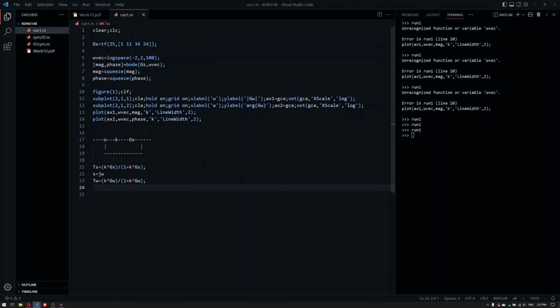In terms of the Bode plot and the frequency domain, we can define instability as tending to infinity, for example, not being bounded. Tending to infinity is the important keyword here, because a ramp function will tend to infinity if t tends to infinity. But if t tends to infinity and we tend to a certain value, then it is bounded in terms of stability. That's called bounded stability. If t tends to infinity and we tend to 0, then that's absolute stability or Hurwitz stability.